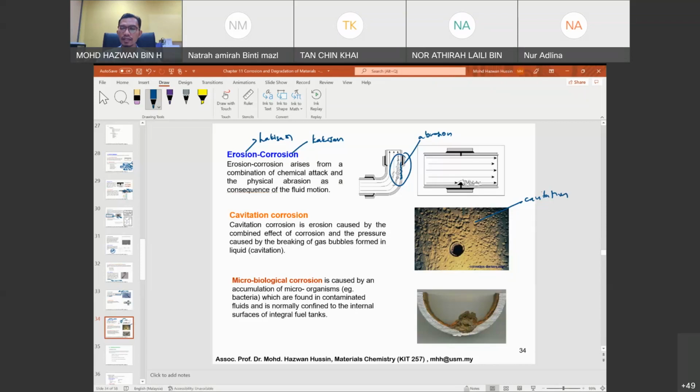It is a result of having a structure with too many bubbles on the surface. Inside these bubbles you have gas, of course oxygen gas, and it is trapped. So it can promote a corrosion process, and finally you'll see the surface become corroded like this.